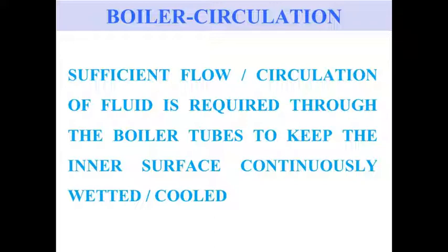So naturally in both the systems, in the boiler there is a fixed steam water separation system like in drum, or we have a continuous system. We have to see that critical heat flux is not attained instantaneously, and there is no failure of tubes.